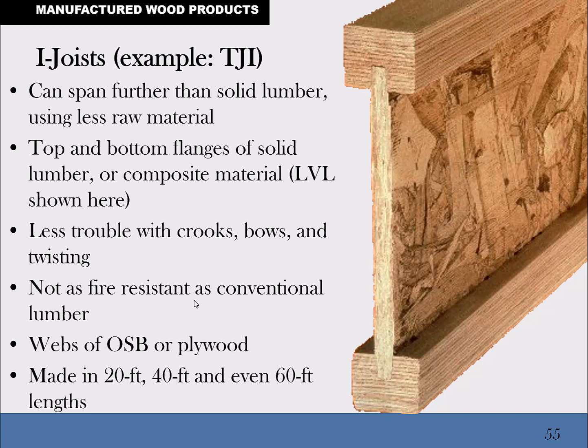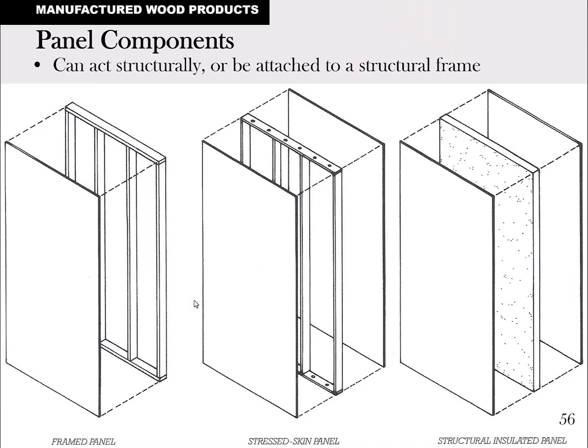So the web of this I-beam is OSB. These things are sold commonly in 20 and 40 foot lengths, and you can special order them up to 60 feet long. And they're all going to be nice and straight when they show up.